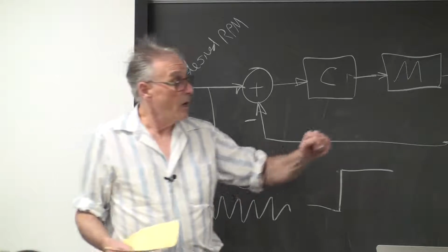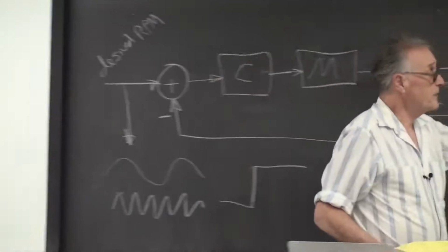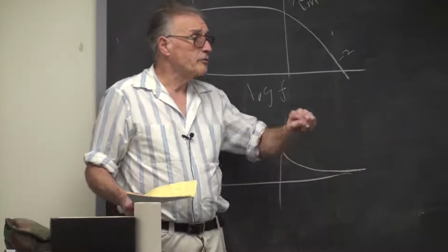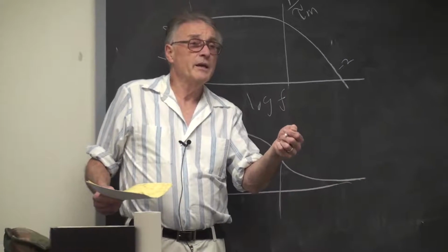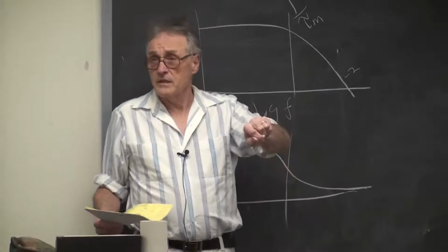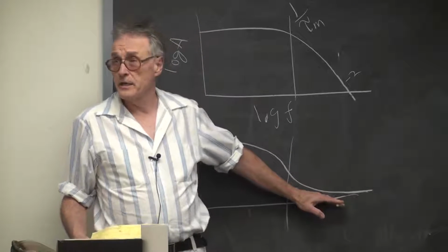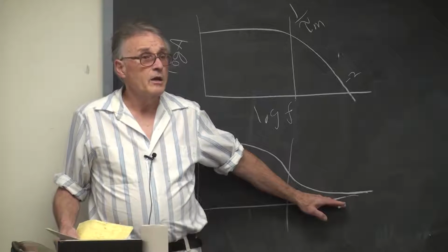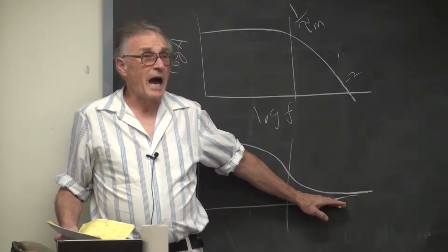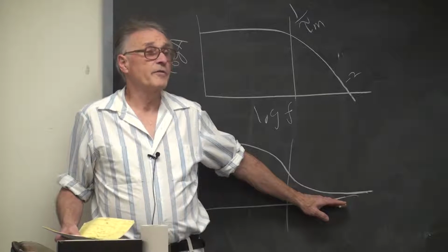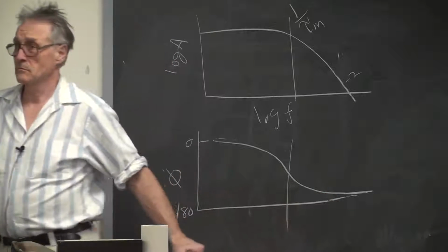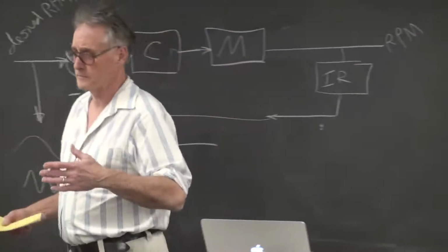And at some high enough frequency, the motor will be speeding up while you're dropping the voltage and will be slowing down while you're raising the voltage. That's what a phase shift of 180 degrees means here. That the direction of the voltage change is going to be opposite the direction of the speed change. This is true in general for lots of linear systems.